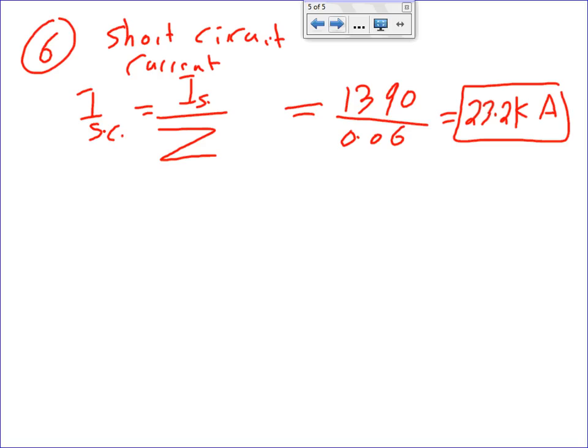50K, so it can handle up to 50,000 amp. This system on the secondary side needs 22K. So can this fuse, at least short circuit wise, handle my system? Amp wise it can't, because it's 65 amp. But at least short circuit wise, it can handle it. So the fuses, guys, that's a fuse, yeah, or a similar fuse.